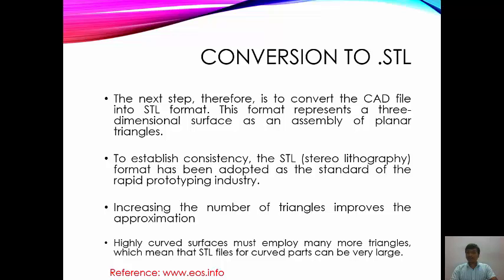Increasing the number of triangles improves the approximation. For a highly curved surface, many triangles will be generated, which in turn increases the size of the STL file. Generally, in most cases, this STL file size will be much larger than the actual CAD model itself. This is a kind of disadvantage in this STL file format.